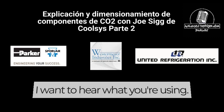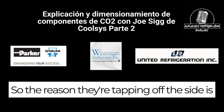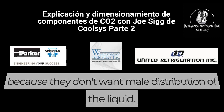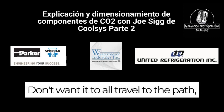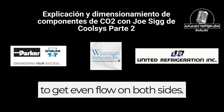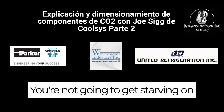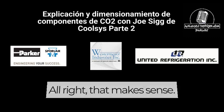I want to hear what you say. The reason they're tapping off the side is because they don't want maldistribution of the liquid. They don't want it to all travel to the path of least resistance. Tap it off the side, you're going to get even flow on both sides. You're not going to get starving on either side of that bushing. Okay, that makes sense.